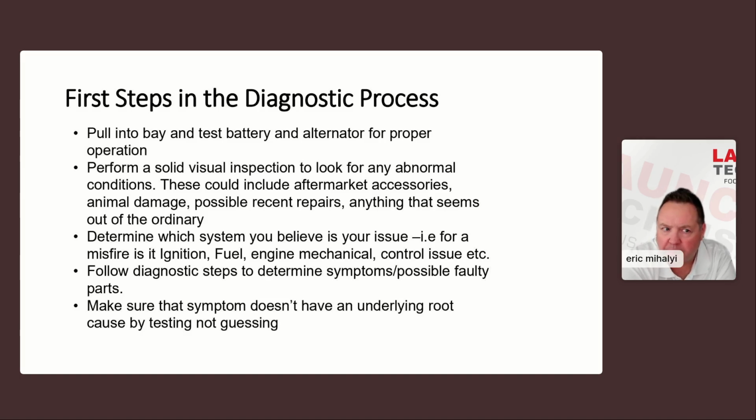Why do you think one coil went bad? I mean, could it be a bad part? Sure. But do you think that there's an underlying cause in cylinder number 4 that could be causing that coil to work harder and burn out faster than the others? I mean, they all have the same number of cycles on them, give or take. Why did one coil go bad over the others? I would start wondering, do I have a lean condition? Do I have a fuel starvation? Do I possibly have a plugged-up fuel injector?